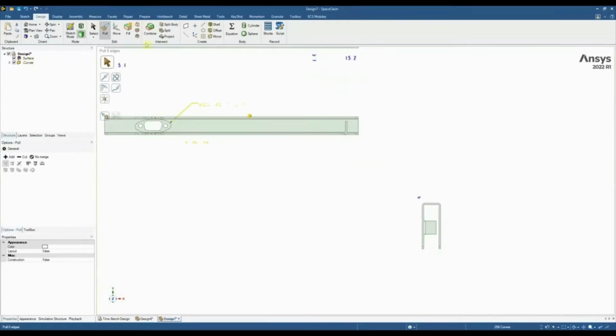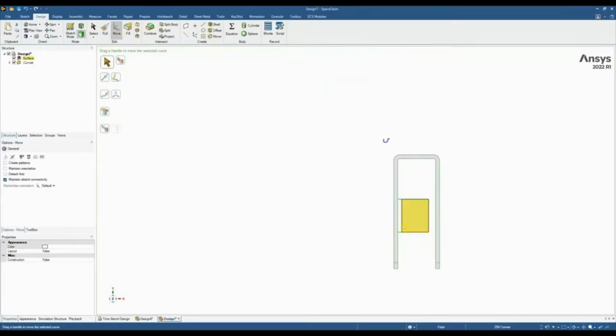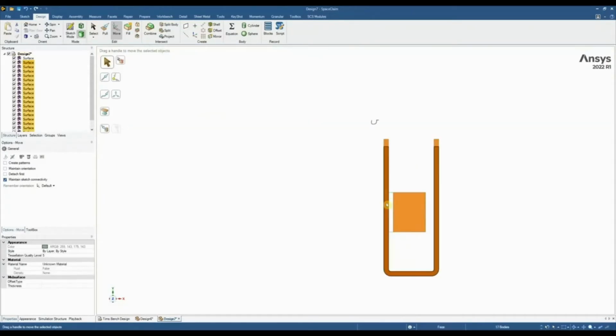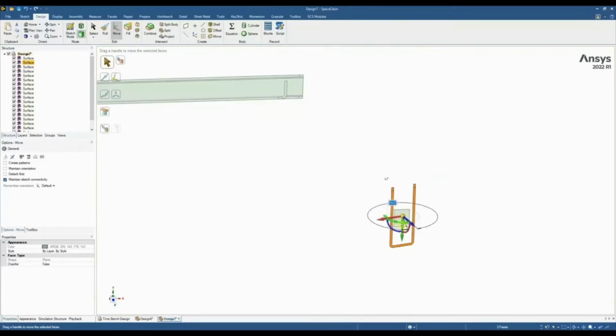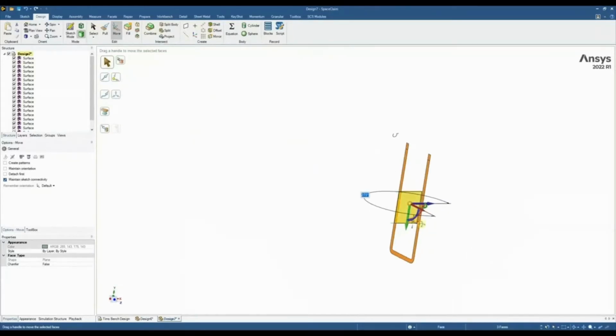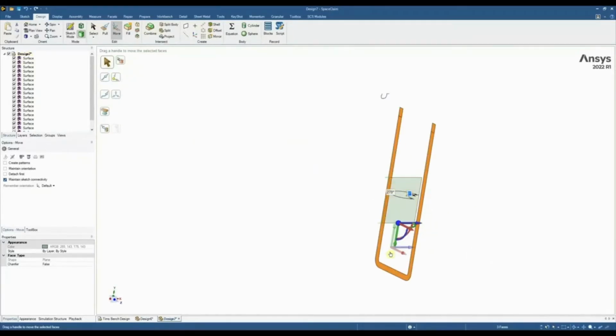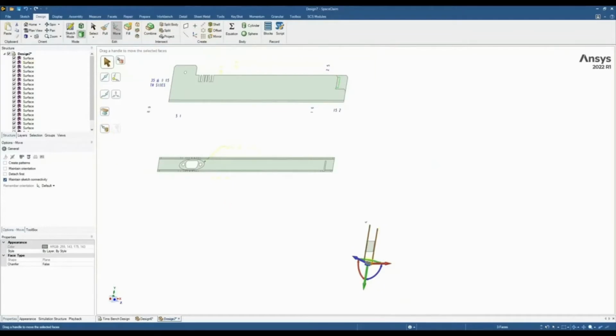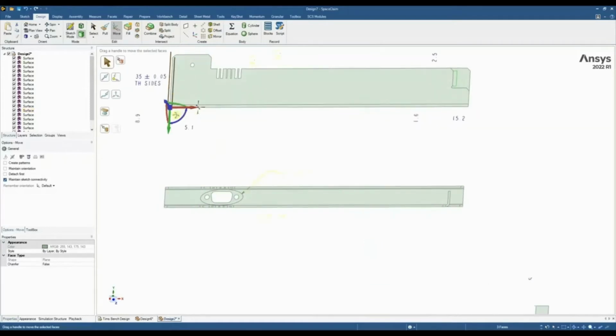To create the 3D model, I'm going to start reorientating a few of these views. The first one I'm going to do is this one here, and I'm going to just rotate it 180 degrees, and I can type 180. And then I'm going to rotate it also 90 degrees, or 270. In this instance, it doesn't matter too much. Once I've reorientated to this position, I'm then going to move my move tool onto the center of this bottom line here, or its bottom edge.